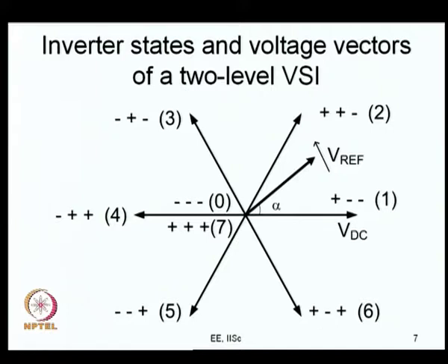Now, in space vector based modulation, you have a revolving reference vector. This revolving reference vector revolves at the fundamental frequency, and its magnitude is indicative of the magnitude of fundamental voltage that you want, and you sample it in every subcycle. Once you sample it in a subcycle, you produce it using a set of the nearest vectors.